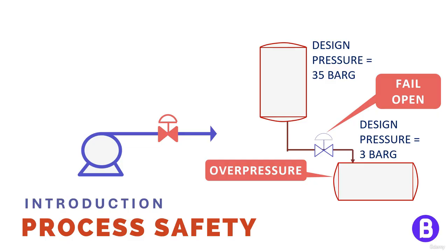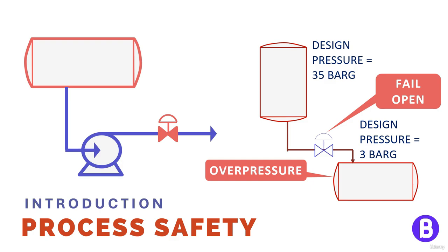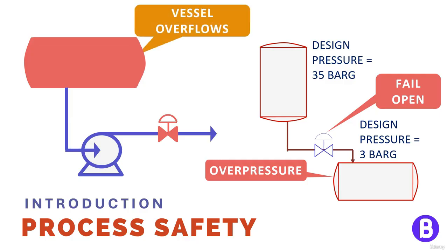We may also have upsets related to the system itself. So, if we are having a vessel from where the pump draws liquid, if the pump stops or fails, the fluid shall accumulate in the vessel and may cause vessel overfilling, which can be a safety issue. So we should study this scenario as well.